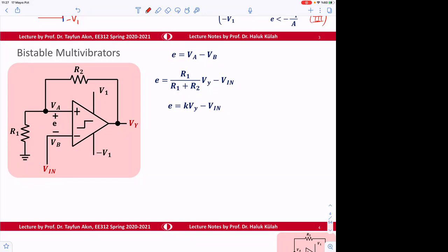Typically for an op-amp, remember, if you want to make an op-amp as the amplifier, we connect this side as the ground, and this is how we connect the feedback circuit. So this is R1 and R2, and therefore we create a gain circuit. Typically the feedback is connected to the negative port.